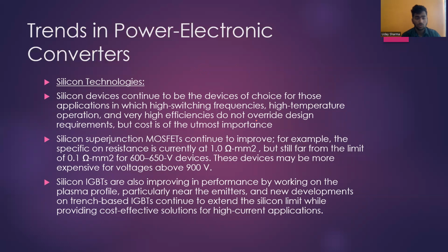Silicon IGBTs are also improving in performance by working on the plasma profile, particularly near the emitters. And the new developments on trench-based IGBTs continue to extend the second limit while providing cost-effective solutions for higher current applications.